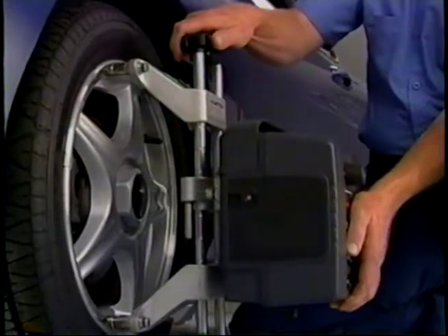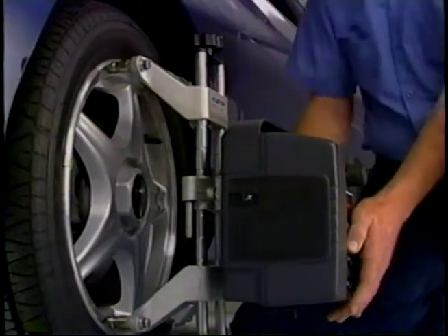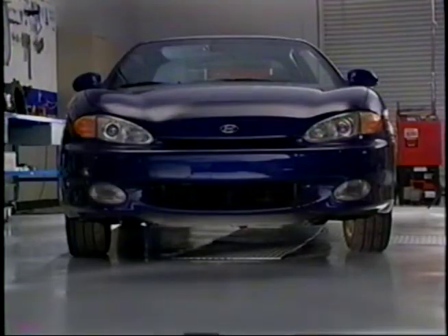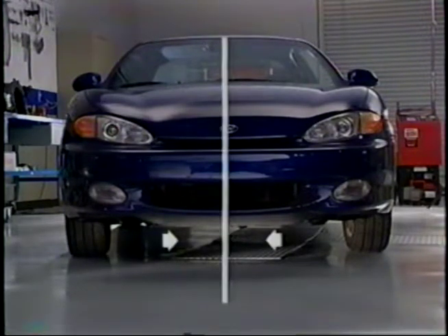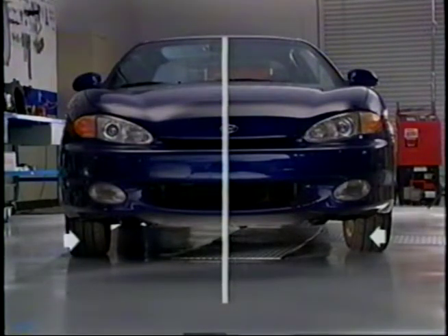If you're diagnosing a tire wear problem, start by checking the alignment angles that will cause tire wear, toe and camber. Toe-in and toe-out refer to the position of the front of each tire to the center line of the vehicle. Tires that are closer to the center line at the front than they are at the back are toed in. Typically, alignment specifications call for a slight toe-in setting because the front of the wheels will push out to zero toe at speed. Excessive toe-in will wear the outer edges of the tires. Toe-out is abnormal and must be corrected. Toe-out will wear the inner shoulders of the tires.